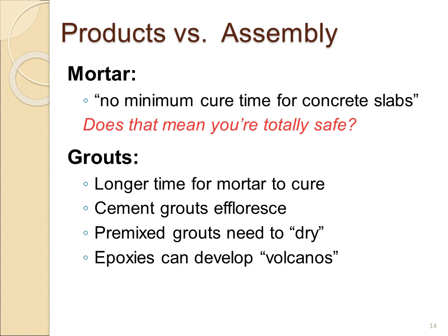So if you're using a cement grout, that cement grout could effloresce. If you're using premixed grouts, they dry by evaporation. So if there's more moisture coming up from underneath it into the grout and around the grout, it's not going to dry as fast as it normally would.